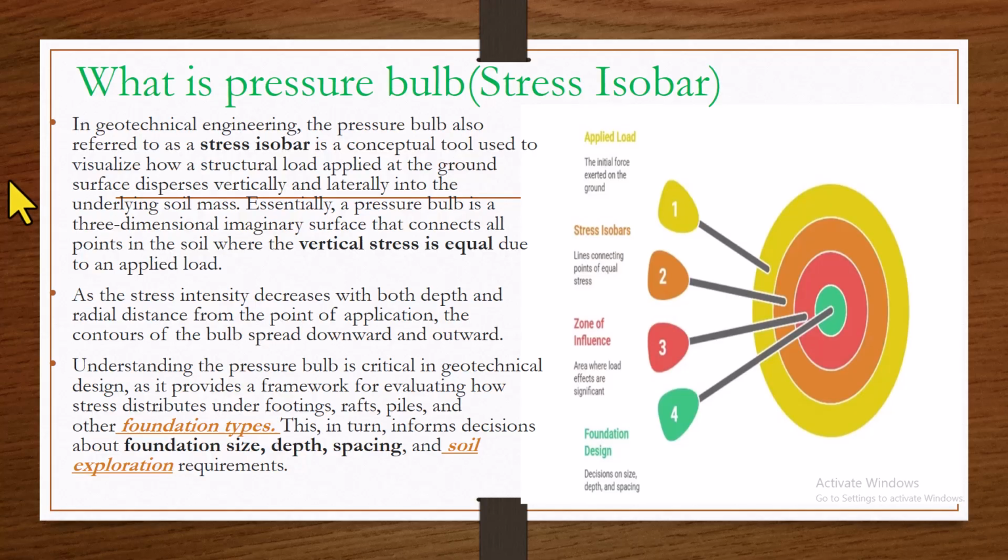Another thing to mark out here is that it visualizes structural load. You want to know the behavior of a load on the soil or at the ground surface, depending on where your foundation or the depth of the foundation is being determined. So we use stress isobar or pressure bulb to visualize the structural load, how the load disperses vertically and laterally into the soil.